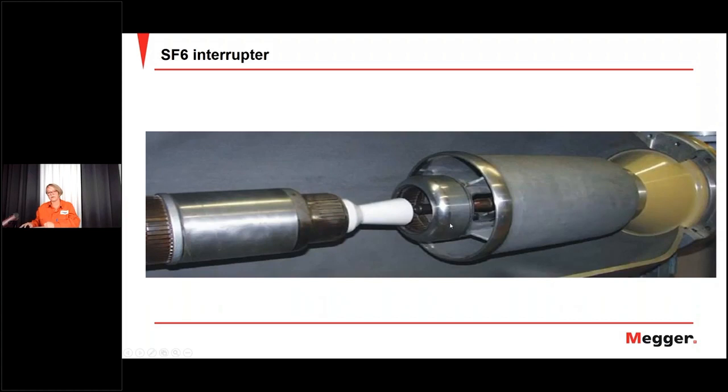So when this breaker closes and opens, you first have contact here inside, and then the main contact. And the important thing is when you do an open, the other way around, when the main contact releases, there is still current flowing through the arcing contact. So the arcing contact can take care of opening. That is the whole purpose of this contact.